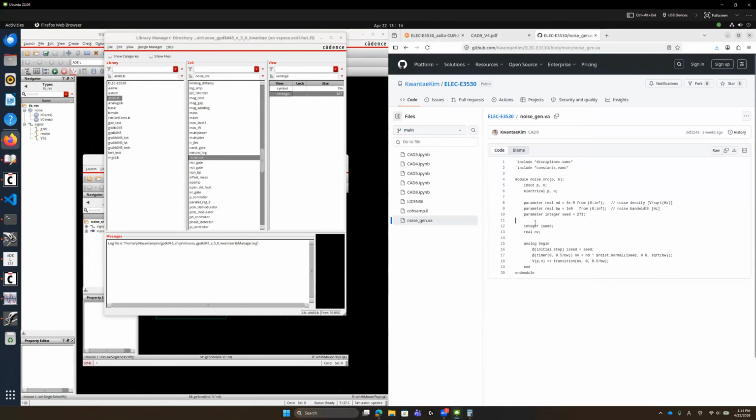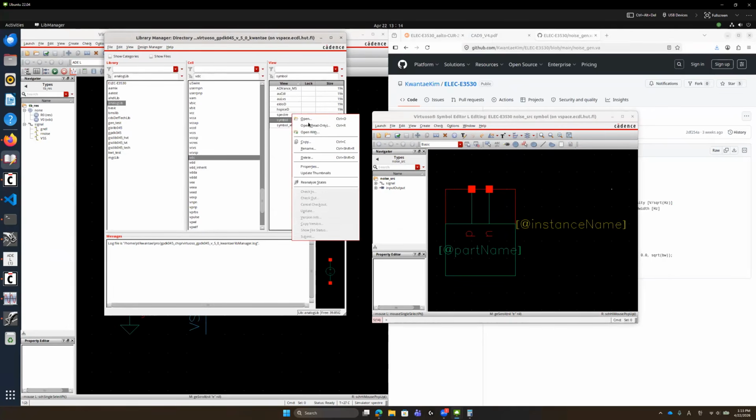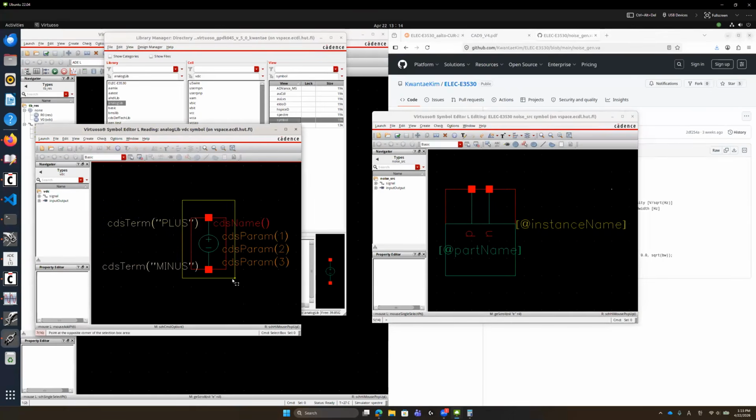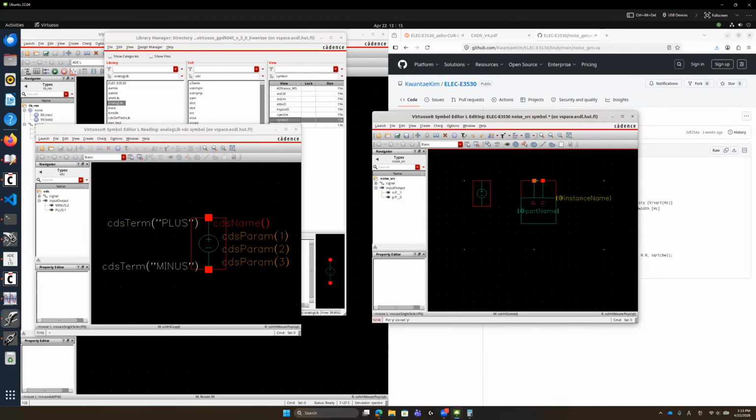So in this new example, the Verilog-A script, we are adding here noise and V for each data point, 0.5 over bandwidth, which is at each data point, a random noise distribution with square root bandwidth, which is adding the value of noise power spectral density, so noise density here. So we are considering voltage per square root hertz, which is more useful in analog circuit analysis, noise analysis. And then we can make this symbol pretty. So if you go to analog only, go to VDC and open read only, then we have this, and you can simply select this one and then copy, paste. Then we don't want the existing port.